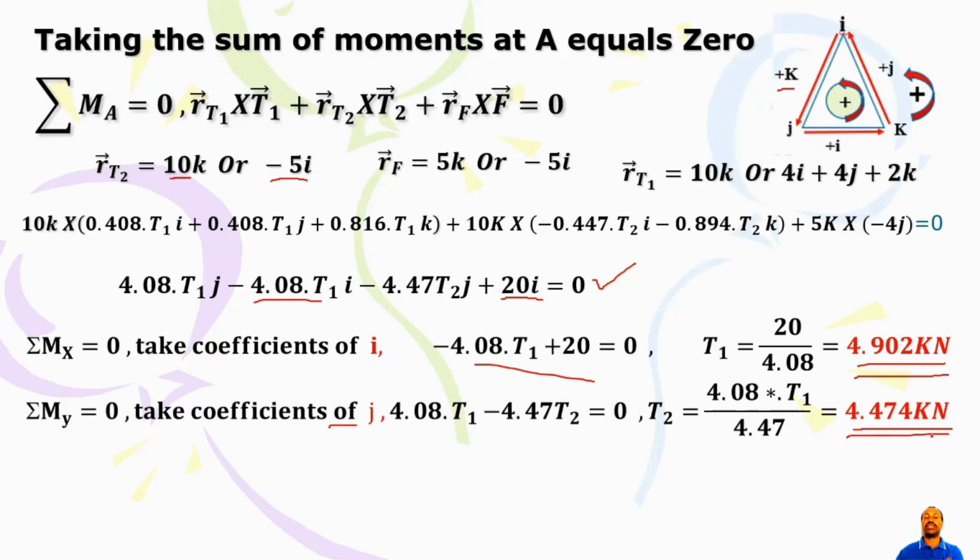So you have, I think, you are forced to use this equation. Why? Because ball and socket joint, you have 3 unknown reactions: AX, AY, and AZ, and also T1 and T2. So I think just 5 unknown reactions you have, but we have equilibrium equation, summation of force in X, in Y, in Z, and the summation of moment. So you cannot finalize. That's why we are using this equation.